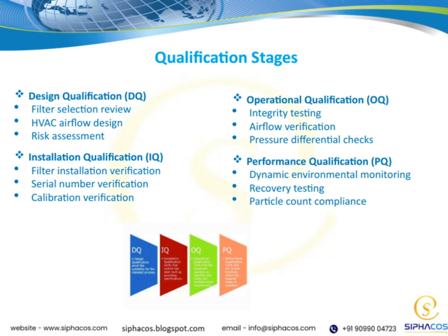Moving on to performance qualification, or PQ, this stage is about confirming that the system performs effectively under real-world conditions. This involves dynamic environmental monitoring, where we track parameters like temperature, humidity, and particulate levels over time. Recovery testing is conducted to assess how well the system can return to normal after a disturbance, such as a power outage or door opening. Particle count compliance is crucial here, ensuring that airborne particles stay within acceptable limits, which is vital for maintaining product and personnel safety. Together, these activities validate that the system consistently provides the desired environment.